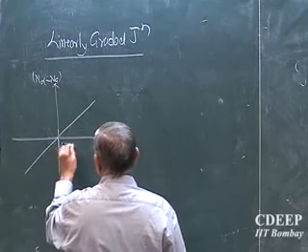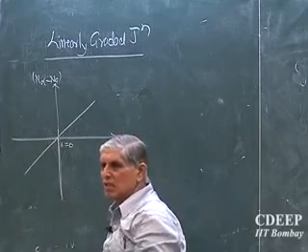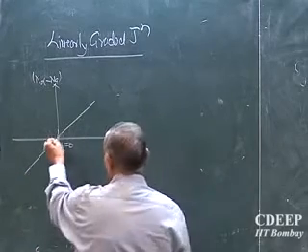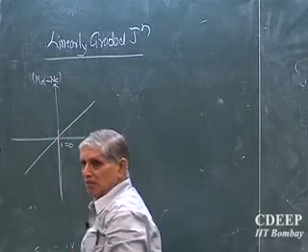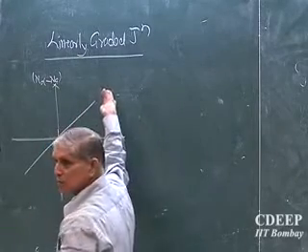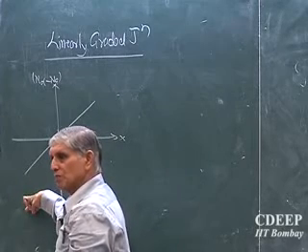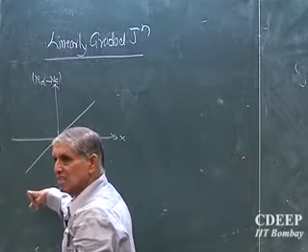So to the left of this, ND minus NA varies linearly with X. So I write with the same slope, ND minus NA increases on the inside. What does this mean? It is becoming N type. What does this mean? It is becoming P type. Is that correct? But it has a gradient throughout.